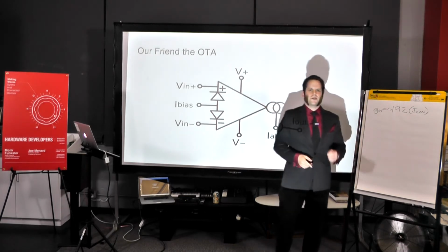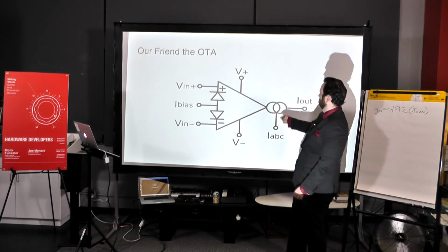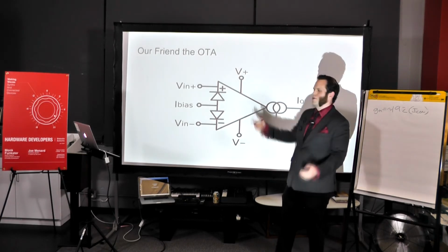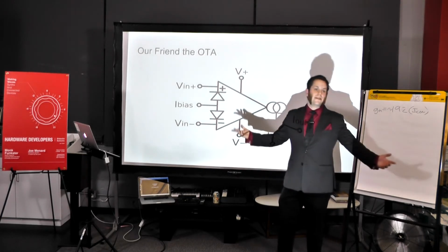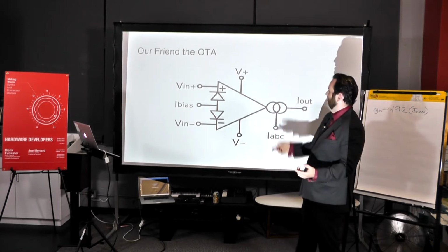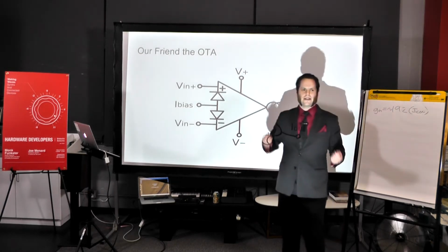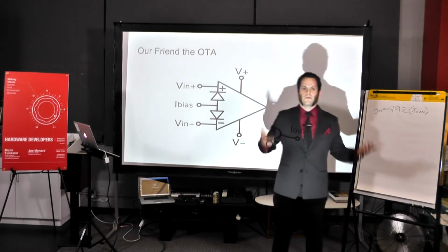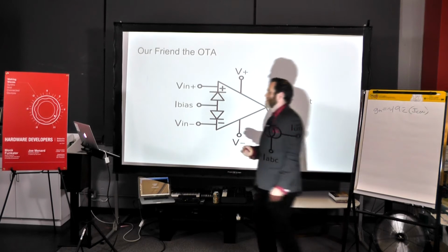It's a really cool device because it means that we can use this to control the gain of that, which, hey, look, if we convert a voltage to a current there, what do we have? We have a voltage-controlled amplifier. It's really neat. It means that I can send a whole bunch of voltages and it will do different things, and I don't have to touch any knobs or dials or do anything else. I have all these automatic signals that will control it for me. It's really cool.